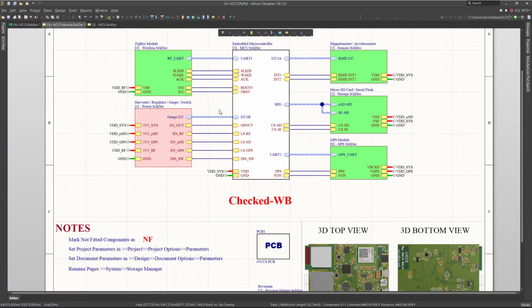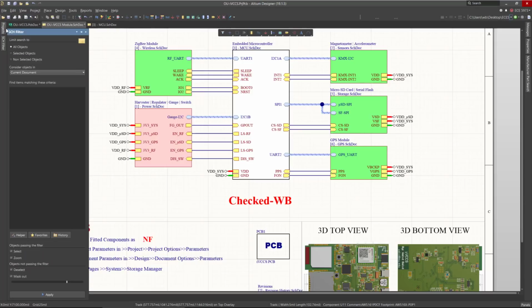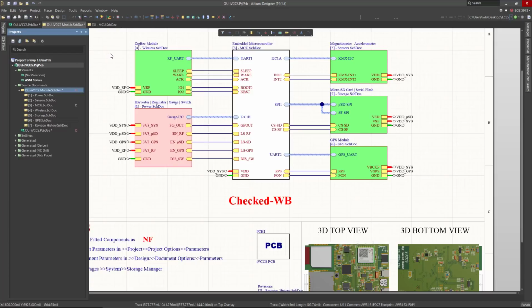Now after you configured the commands, you have the bars, the panels you want to be open, the sizing. Basically, you can save the environment layouts into a file. So if you move to a different machine, you can just transfer this file and load it into Altium, and the Altium environment will be configured according to this configuration you have.